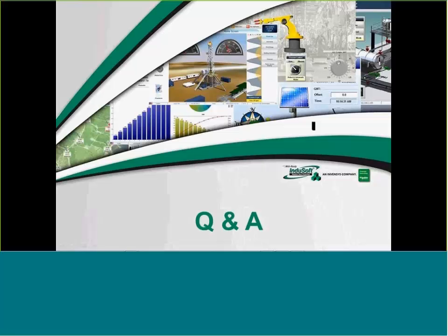Great, thanks. Another question that came in says, do I have to install a SYSMAC Gateway on the runtime machine or only on the engineering station? And will it be transferred to the runtime machine while downloading the IWS project to it? Okay, so that's another great question. And just like you have to install InduSoft Web Studio on both a development machine and a runtime machine, the same does apply to SYSMAC Gateway. That's installed on the runtime machine because it is a full-blown communications gateway.